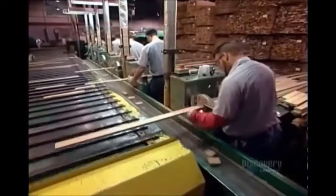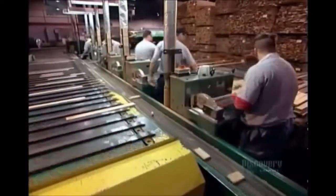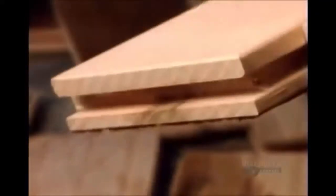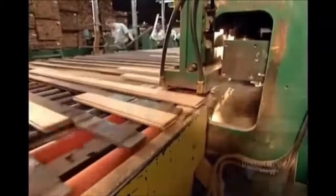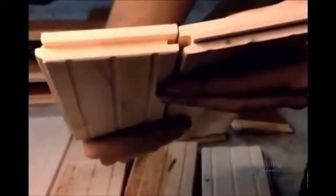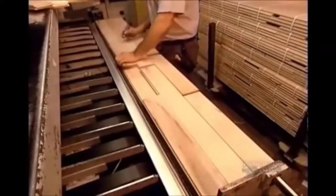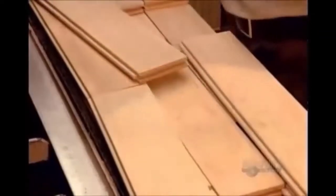Using cross-cut saws, workers remove any faults in the wood and divide pieces that have noticeable color variations. This is the first step towards sorting the wood by grade. Now a machine called an end matcher carves a tongue and groove on the two ends. Here's the view from inside the machine. Workers check once again for faults. Then, assessing quality and color, sort each piece by grade.